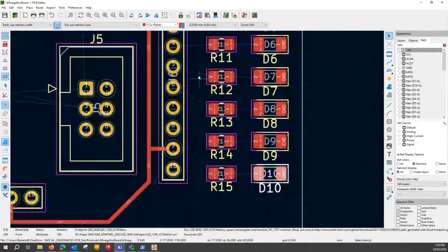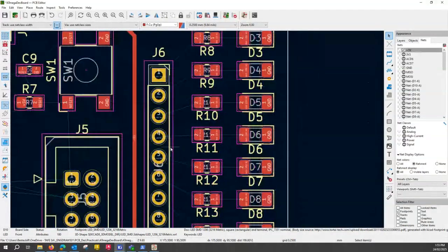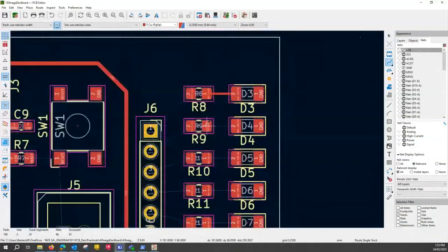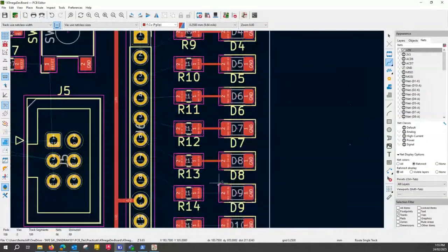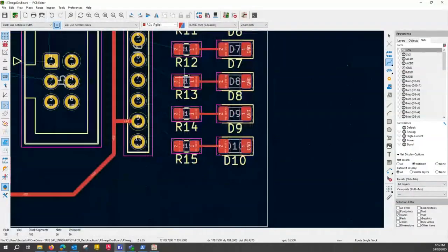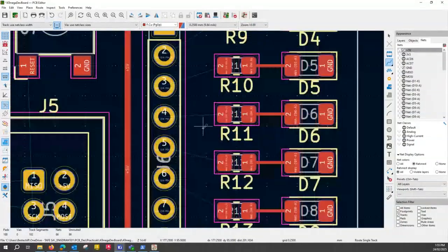So I usually start in the middle and go out. Let's just connect. We'll do direct connections first, the easiest one. So we've got our net class, which is 0.25. We do everything using the same thickness on this board. Nothing too fancy. Okay, and now I'll just run it from the center. So let's say I'll start with pin 4, and I need to run it there.